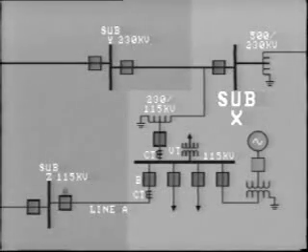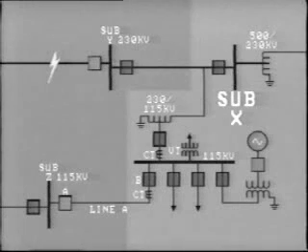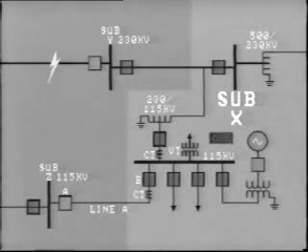Breaker A at 115 kV substation Z trips for a remote fault on the 230 kV system. With the help of the oscillographs located in substation X, we were able to spot the problem and correct it. In substation X, the oscillograms monitor the transformer breaker's A-phase current and the zero sequence residual current.